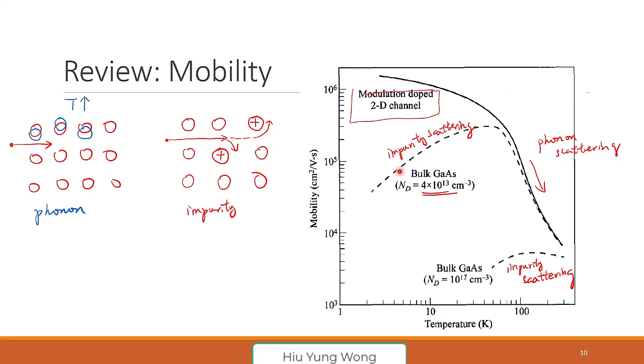Professor, when the electron travels through vacuum, we don't see this impurity scattering effect, right? Yeah. If you have vacuum, you don't even have phonon. The electron used to travel through the vacuum, so if we use a vacuum tube, we're expecting a high mobility without this type of effect. In a vacuum tube, you don't even talk about mobility because there's no scattering, right? Mobility is what? Given an electric field, you travel at a certain velocity.